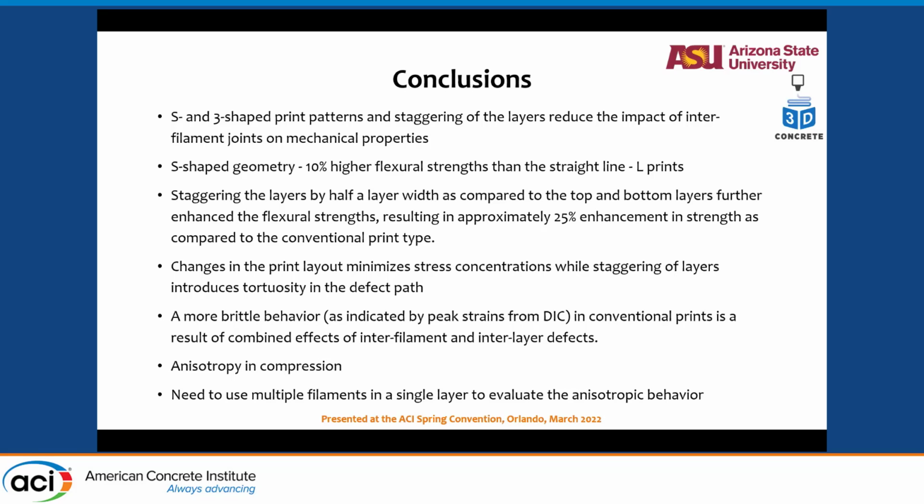If you do flexure, if you have a beam and you're loading it perpendicular to the direction of the layers, the layers are this way and the filament is this way, right? So multiple layers and the filaments this way. If you load like this, with a 4-point or 3-point loading, and you are avoiding that interfilament joint, then you are actually loading this beam like something with a notch right in between.